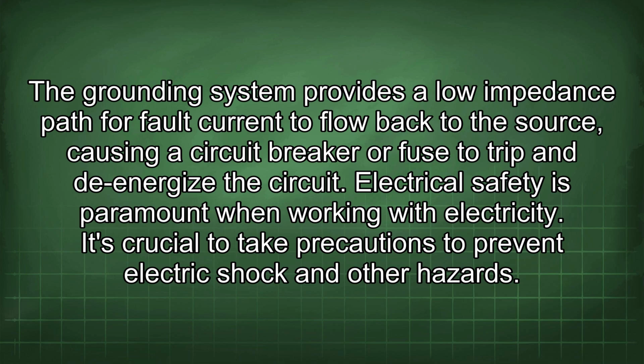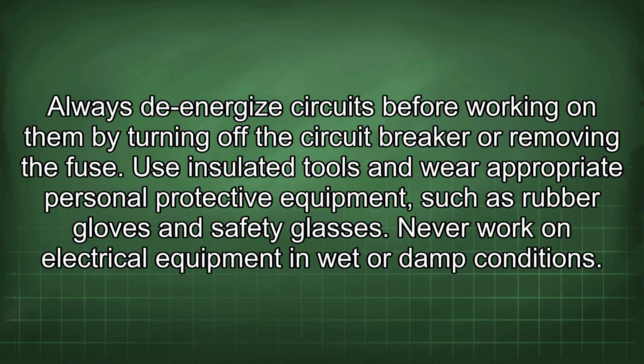Electrical safety is paramount when working with electricity. It's crucial to take precautions to prevent electric shock and other hazards. Always de-energize circuits before working on them by turning off the circuit breaker or removing the fuse. Use insulated tools and wear appropriate personal protective equipment, such as rubber gloves and safety glasses. Never work on electrical equipment in wet or damp conditions.